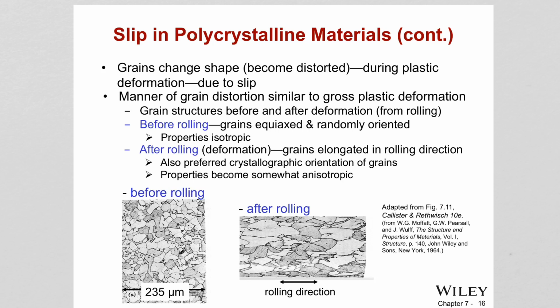Because there are no grain boundaries, there are no differences in orientation in single crystals, so the dislocations flow easily when you reach the most favorable condition. But in polycrystalline materials there are a lot of obstacles to dislocation motion, starting from the grain boundaries and different orientations in grains, and therefore polycrystalline metals are stronger than their single crystal form. Okay.